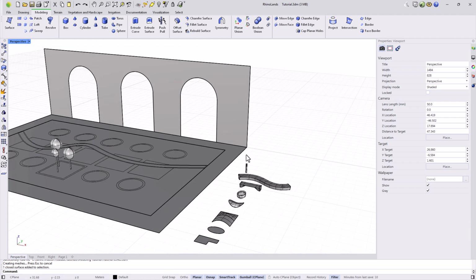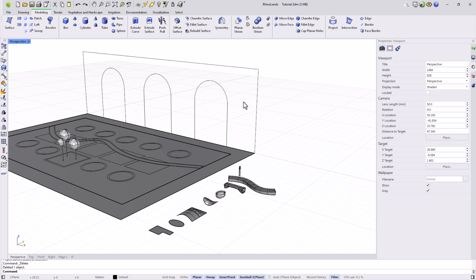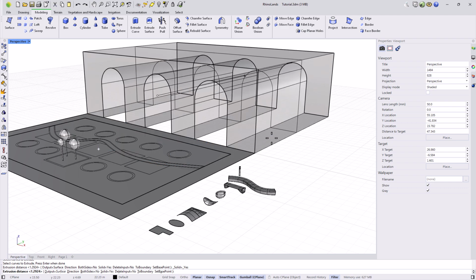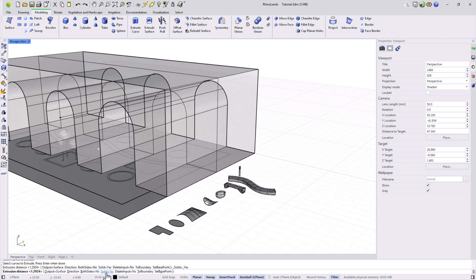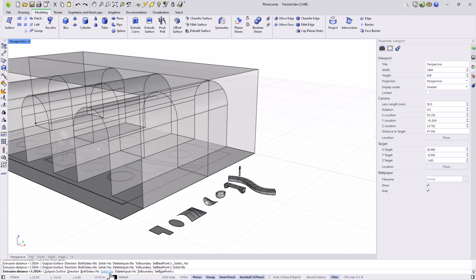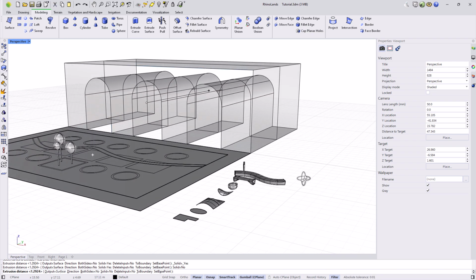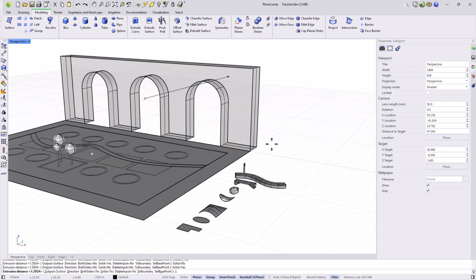We can also create custom solids from curves and surfaces. With the curve extrusion tool, we can transform a curve into a solid by extruding it. For this wall, instead of cutting the surface, we can directly select its outline, right-click, and move the cursor to the side. We want to extrude it, and we can enter a specific value for its thickness. If in the options of this command we select solid, yes, we will get a solid as a result. On the other hand, if we select solid, no, it will only generate the extrusion of this curve.